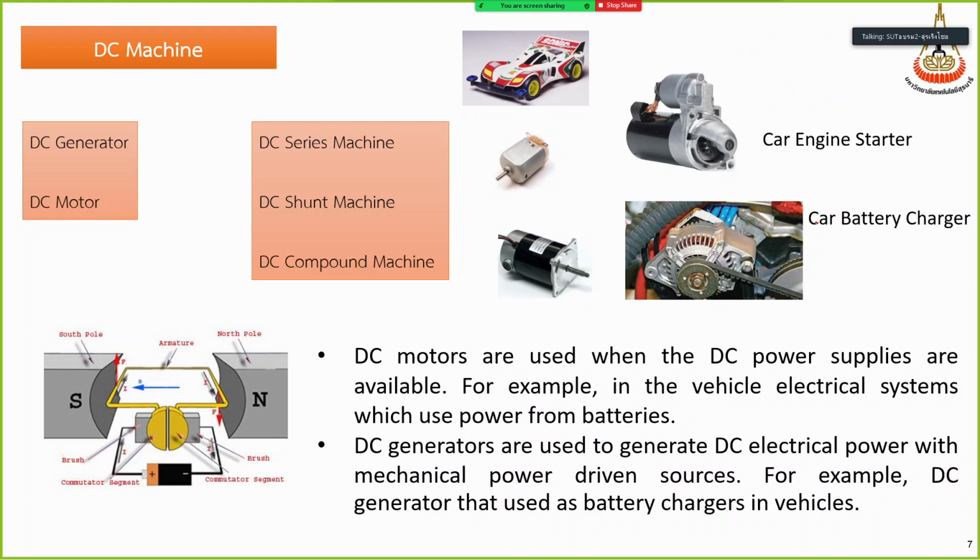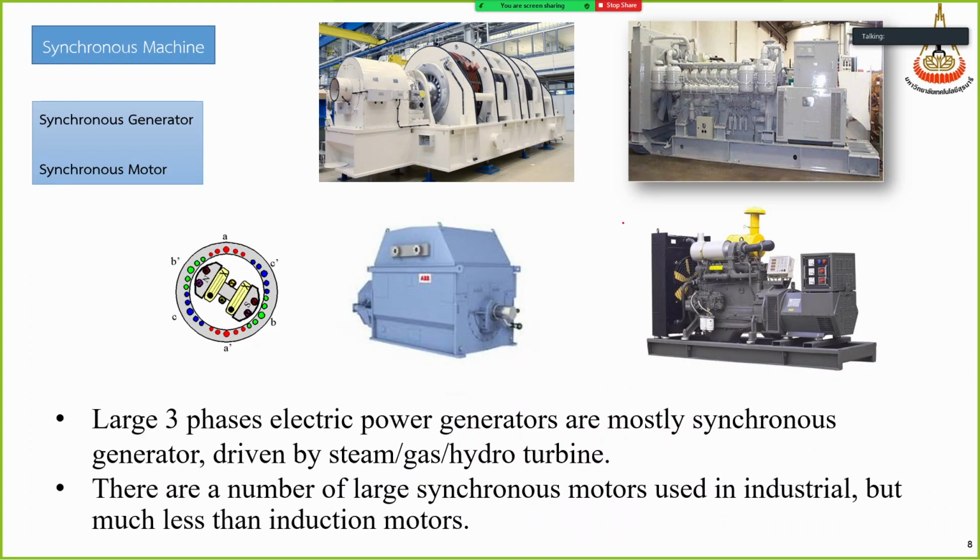So if you turn off the engine for too long, your battery will discharge or leak, and will have self-discharge, and you cannot turn on your car from that battery. So usually the battery needs this charger. If you park your car for too long, maybe after one week or two weeks, you need to start it up, and it is charged by this DC generator in your car.